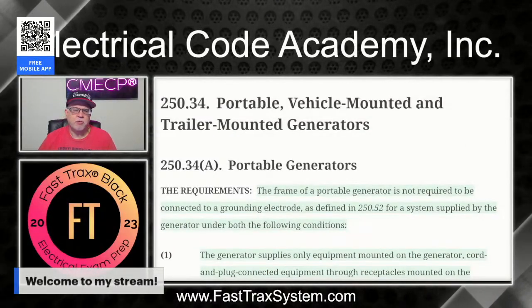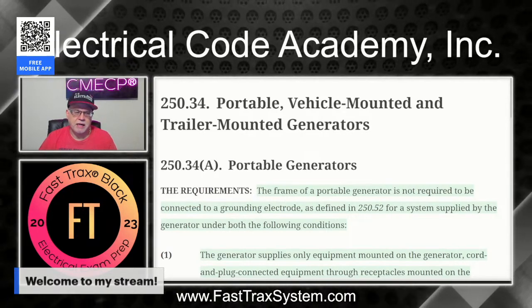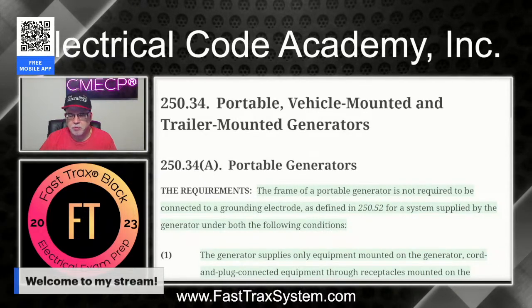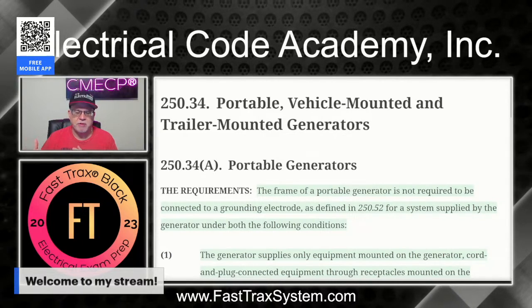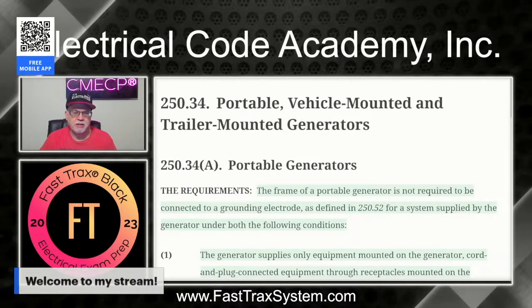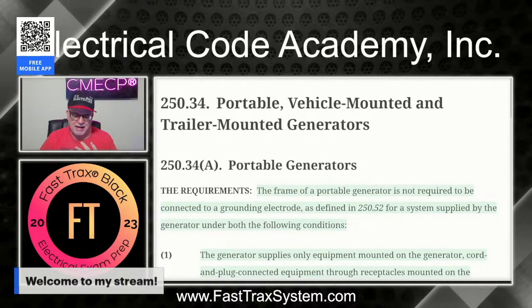All right, so we're going to be looking at 250.34 portable. Now we're not going to be looking at the vehicle mounted or trailer mounted generators in this episode. We're just going to be focusing on portable generators. And there's a lot of stuff that's quite confusing about generators that we've learned over the last couple cycles. Is that, you know, when would you want one that is the frame of the generator bonded to the neutral point? And when would you want to have, or when could you have a floating neutral type generator? So we're going to be looking at those and trying to break it down to maybe simplify it a little bit